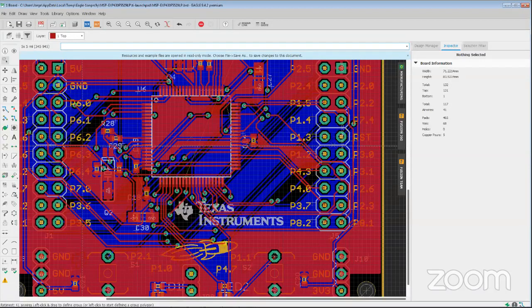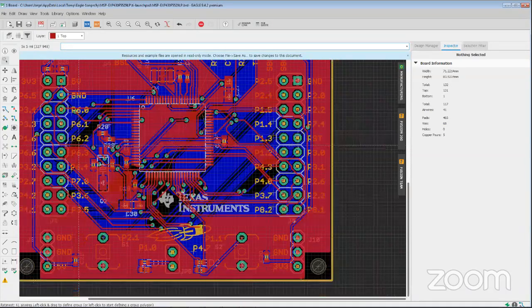And as you start making changes, you start deviating from what the autorouter had before. And eventually it gets to a point where Eagle can't reconcile the two. So a very key important point with working with the autorouter is that you must hit end job at some point. You have to hit end job. So let's go ahead and show you how you can do this.